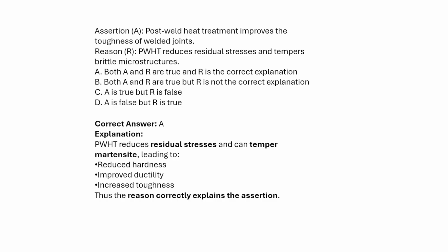The post welding heat treatment improves the toughness of welded joints because it changes the microstructure from martensitic to pearlitic or other microstructures, reduces the residual stresses, and tempers the brittle microstructures. It reduces the hardness, increases the ductility, and increases the toughness. Thus, the answer is correct.